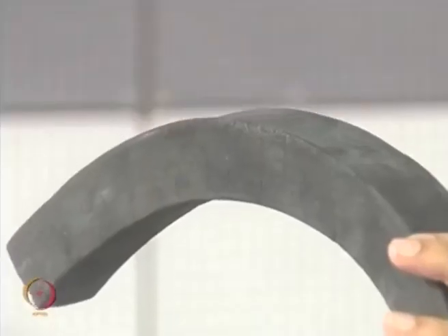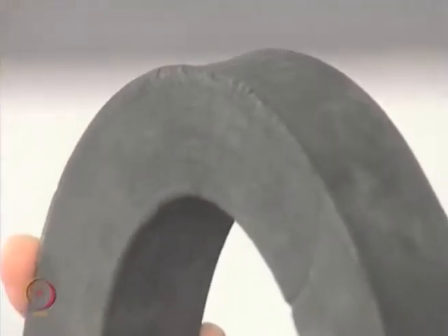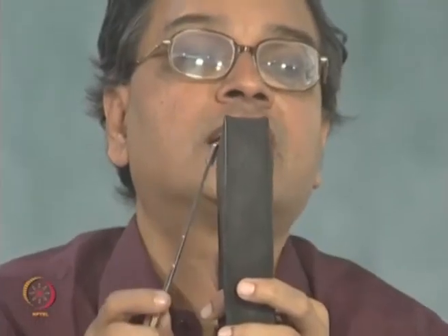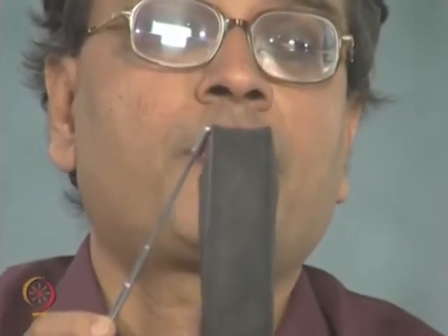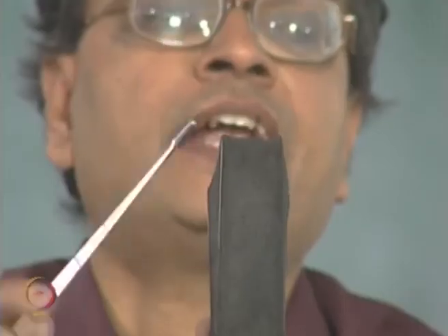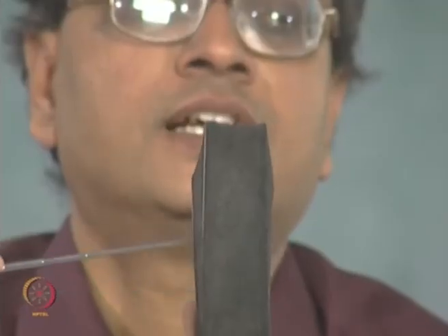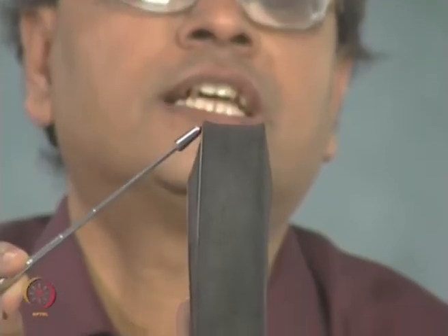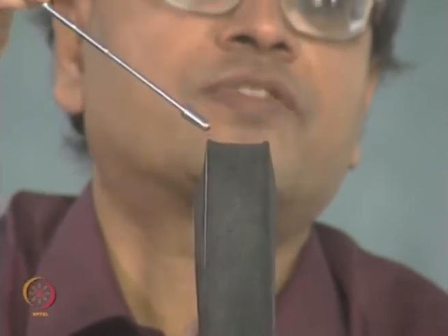I have said that in addition to this you also have strain because of the Poisson effect, and what you find is, if you look at it sideways, I have a bulge at the bottom and it is not bulging out at the top. Why has this happened? In the way I have bent, this fiber is subjected to tension and the inner fiber is subjected to compression, and because of the Poisson effect, the bottom portion bulges out and the top portion narrows down. And you also see one more interesting thing, you have additional curvature here because of this, and